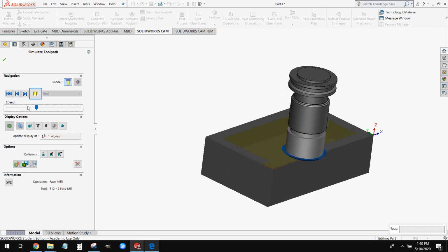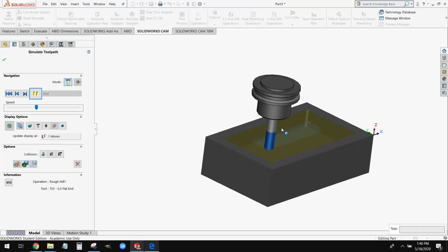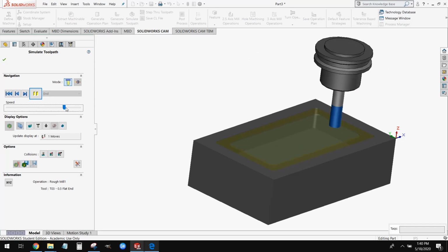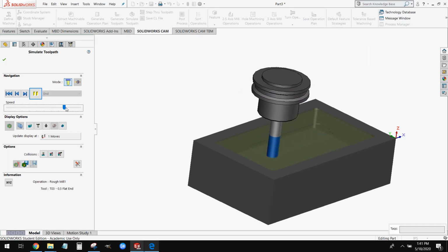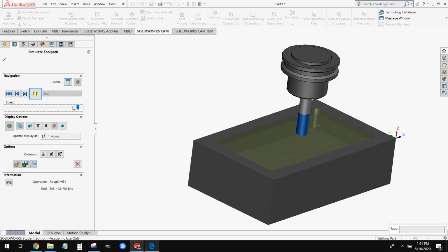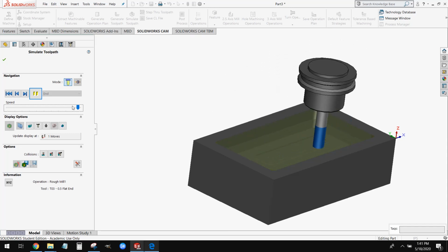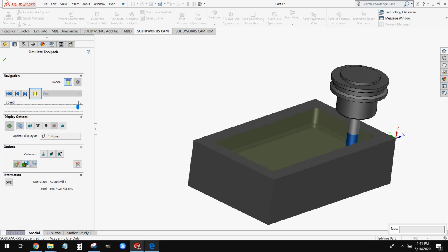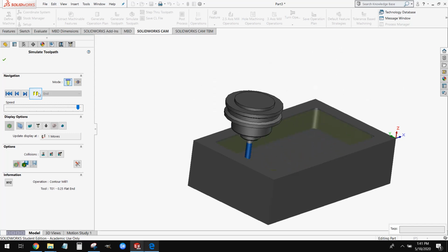And then after it does this, it should come in with the 1/2 inch end mill. And that looks pretty good. I'm going to speed this up here because it's going to take quite a lot of passes with that 1/2 inch end mill. Now, the only reason we're using our 1/2 inch end mill for this is just because this is a common tool that we have in the Wentworth shop. If we had access to 3/4 inch, or in this case, even probably 1 inch diameter cutters, we would definitely use that for time savings.